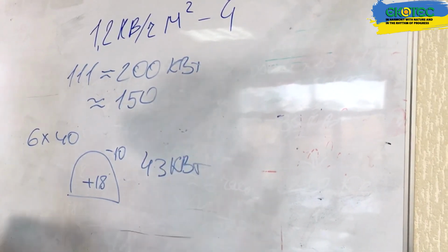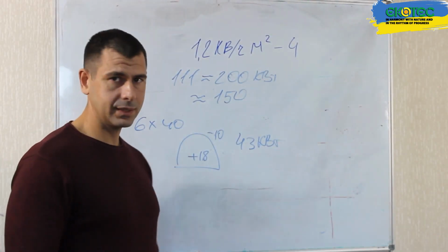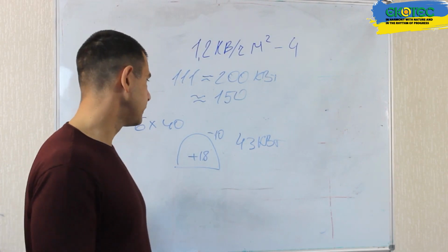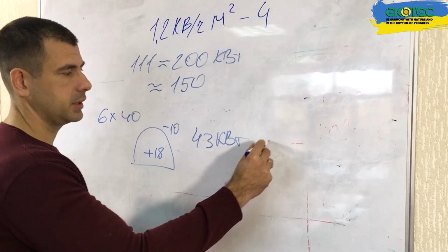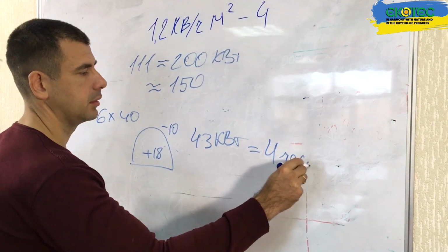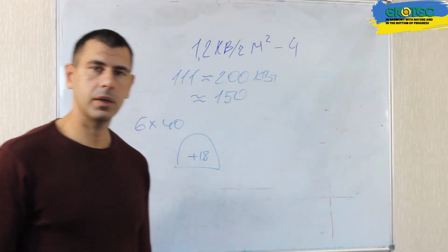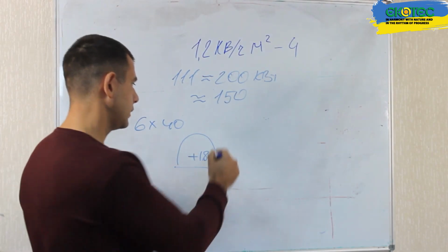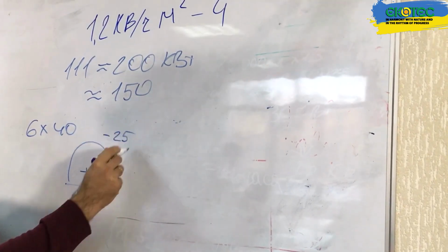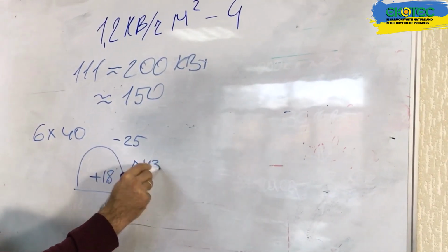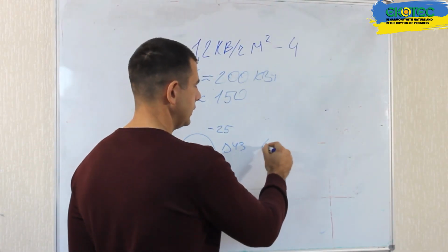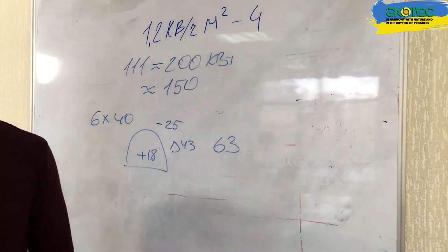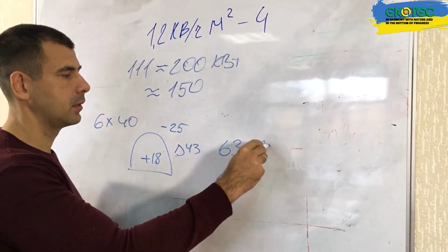In spring, when the sun is at its peak, we can accumulate 200 kilowatts of heat. With this heat, for example, in April, we can maintain a constant temperature of 18 degrees Celsius at night, even if it's 0 degrees outside, meaning we can completely do without heating. The greenhouse temperature will gradually drop from 25 to 18 degrees Celsius and stabilize at 18 degrees Celsius by morning, even if it's 0 degrees outside.